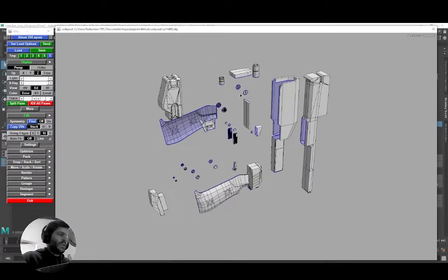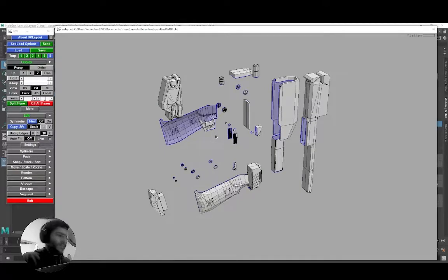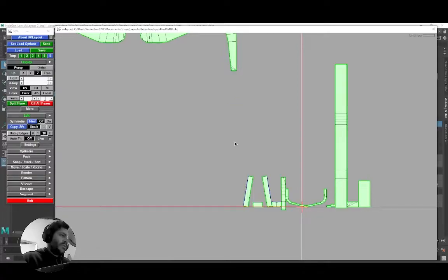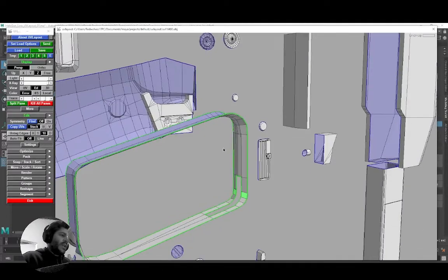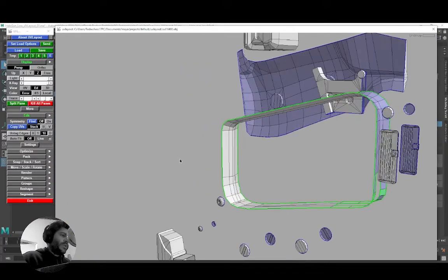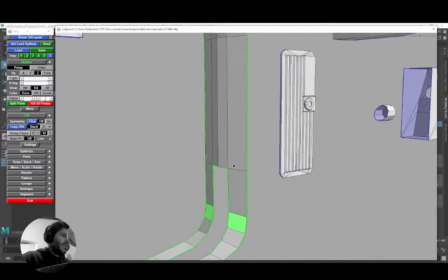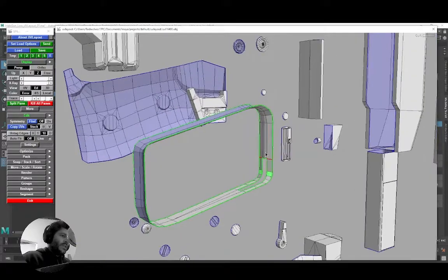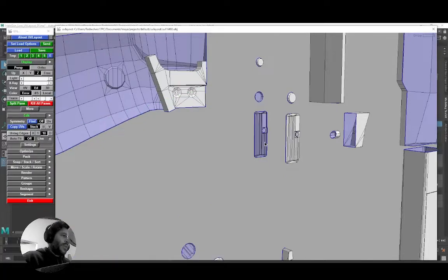but we can't see the mesh because it's dropped into the UV space. So if you want to edit the mesh again, you need to go to the UV space and press Shift D to send it back to the UV editing window, and here you can add the cut that we're missing. For instance, we can add a cut, I don't know, maybe here. So this can be unfolded, and again press enter and drop it again to the UV space.